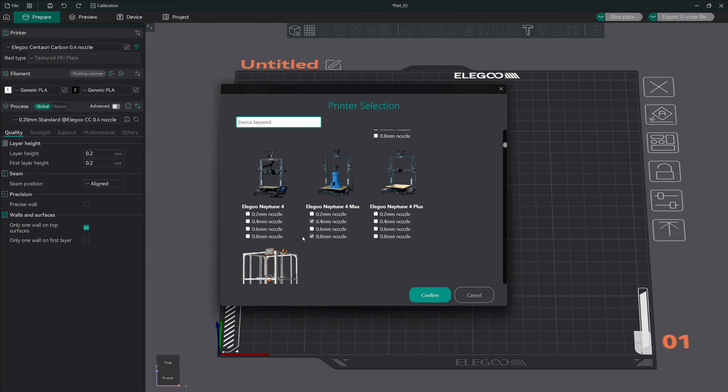If you're not sure of the difference in nozzle sizes, most printers come with a 0.4mm nozzle, which is pretty standard. The 0.4mm nozzle can handle pretty much every kind of print. Now, if you're looking at printing small figurines for a tabletop game, then you would want to purchase and install a 0.2mm nozzle, as it will give you a much higher quality print for those small details.